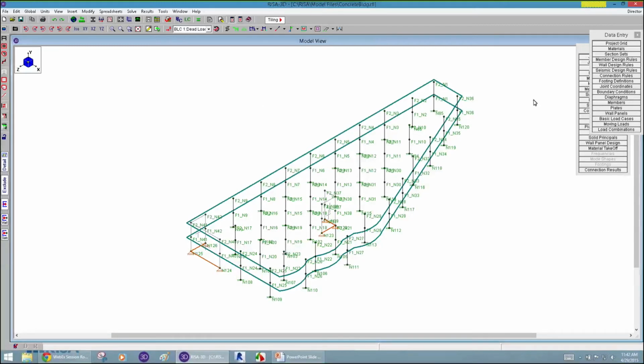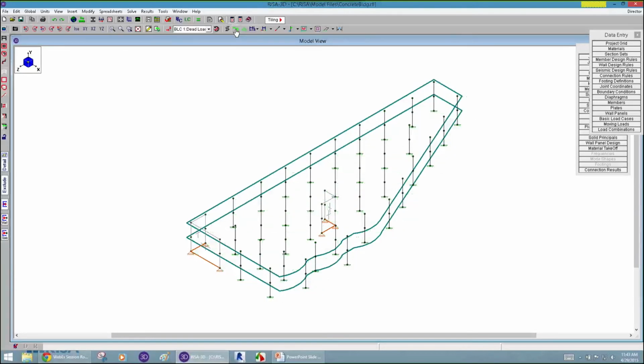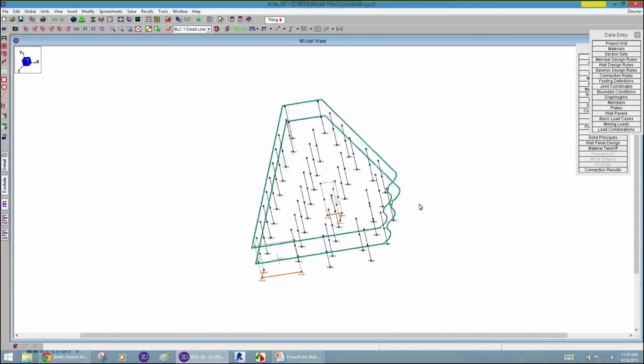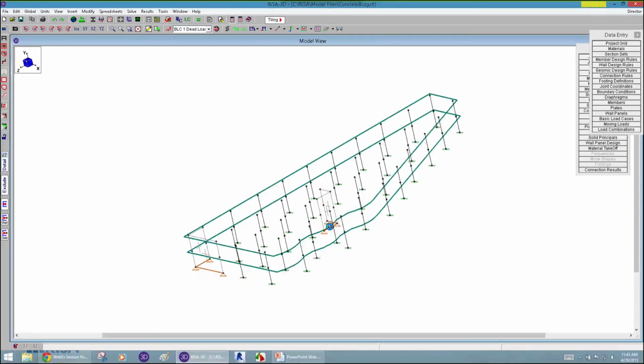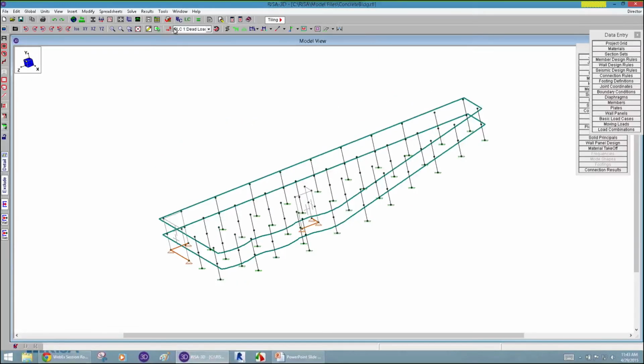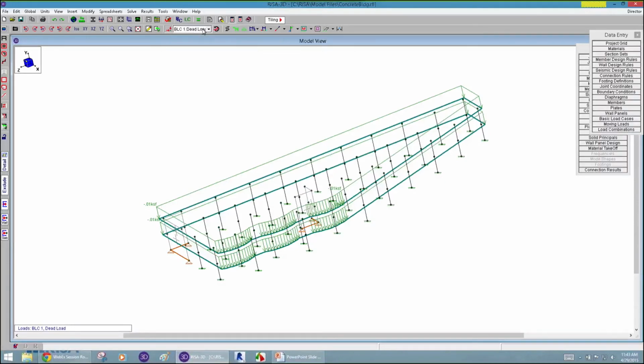What you'll notice happened right away is that I got a diaphragm edge. It's a slightly different color than you're used to if you're looking at the rigid diaphragms. This is going to be a little greenish color, and that indicates that it's our semi-rigid diaphragm. And this semi-rigid diaphragm right now just gives us the outer perimeter of that diaphragm. When we come over from Risa Floor, all the loading comes across with it. So you'll see the dead load is listed on that diaphragm, on that slab. The live load is listed on the slab.